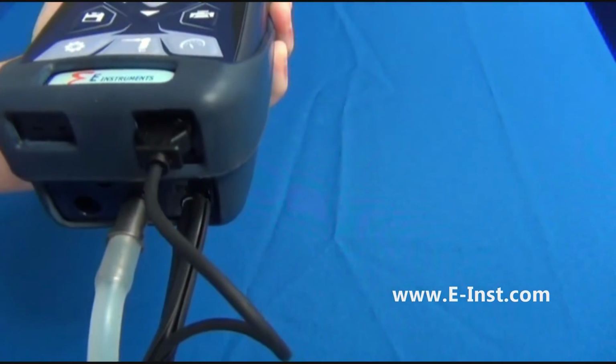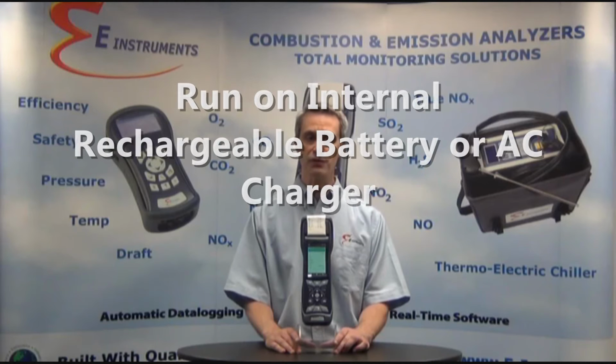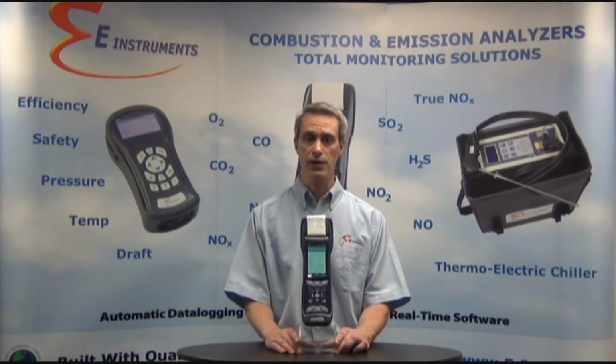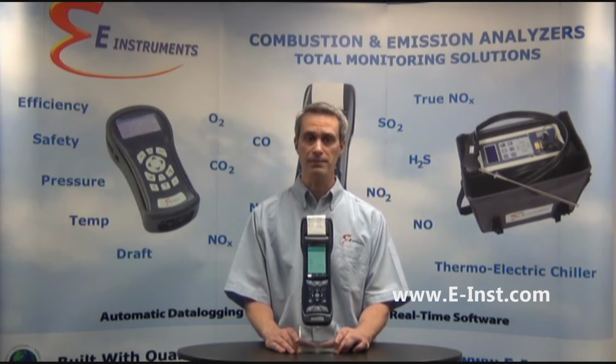Now you are ready to insert the probe into the stack and begin the combustion analysis and emissions monitoring. The analyzer runs off rechargeable battery power or AC power. If you plan to run off battery power, make sure to charge the unit the night before while the unit is turned off. The analyzer can run for 8 to 10 hours on a fully charged battery pack. It is recommended to run off AC power as often as possible.